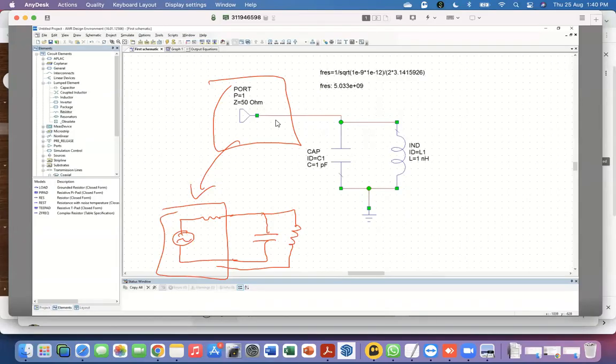There is this transient solution and then there is the steady state solution. When you write down solutions for oscillators, you always write down a steady state solution and you plug it in and you see it. That is after the steady state is reached. And that is where the entire scattering parameter picture, which is always in frequency domain, is always in steady state.